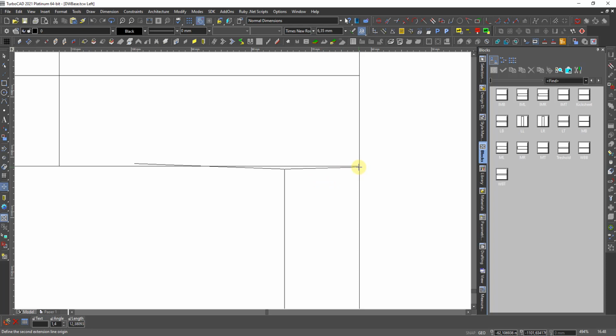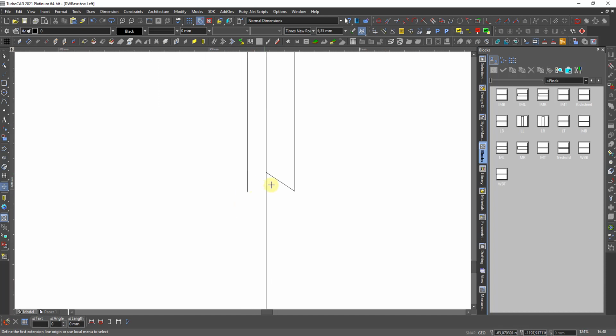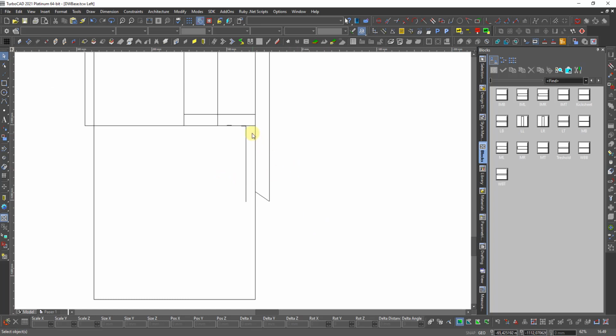To V is 1249. Okay. I don't want that, but I want this longer. I say from V to V, there is 13. I add 15 millimeter extra, so this one coming a little bit more down than this. I think I need to close and re-open the drawing because the reference point was set in that corner, not in the middle.